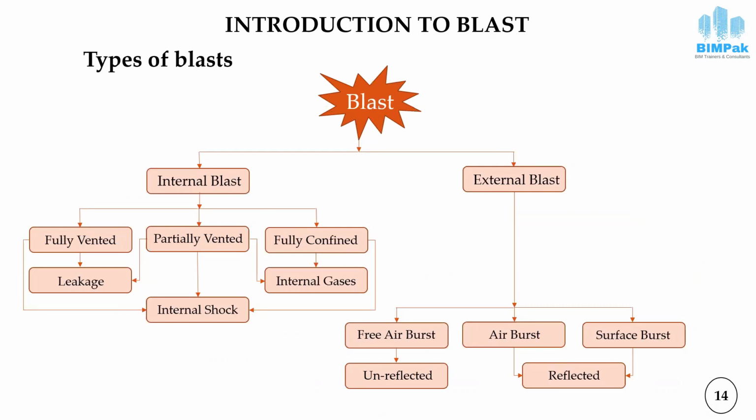There is another type of classification of blast, and it is on the basis of the location of the explosive material relative to the target. In that case, a blast can be an internal blast or an external blast. As is evident from the name, internal blasts are those which take place inside the building. That can be further classified as fully vented, partially vented, or fully confined.